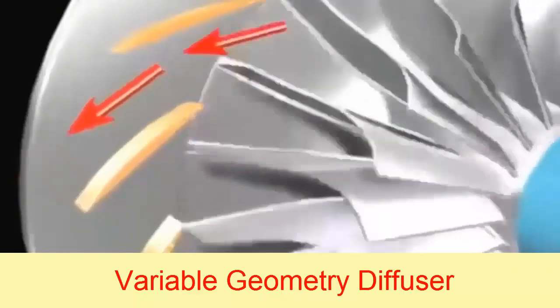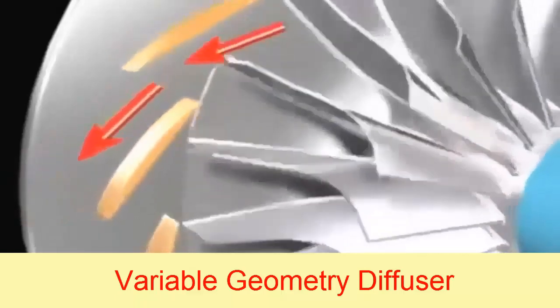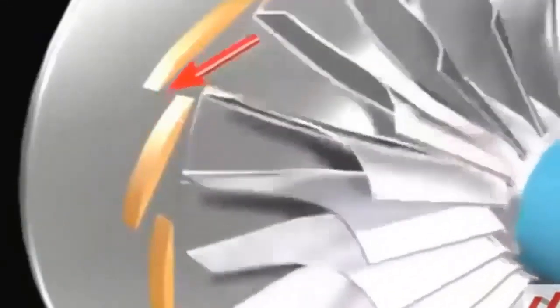Logically we cannot have, as we said a minute ago, the same refrigerant flow section when the amount of gas being handled is less than when it is greater. There we see how the area is changing. In this way it is tied to the refrigerant charge. This diffuser is going to be in charge of partly transforming the velocity into pressure, and the velocity is transformed into pressure when the area of passage is being changed. So kinetic energy is converted into energy in the form of pressure. I think that with this animation it is very clear, at least to begin to learn more about the operating principle of these machines.